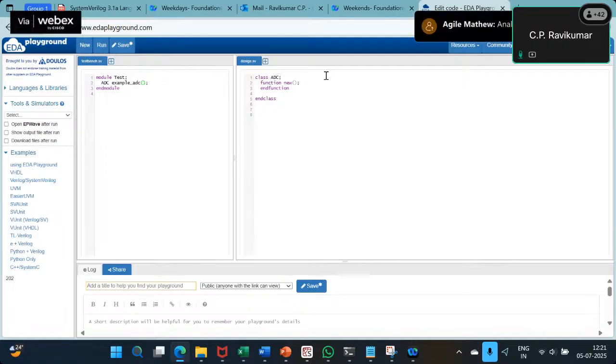Of course, we can keep a register. Okay. So maybe we can keep the accuracy or resolution is also something that we may have to give. Maybe we can say I want an 8-bit ADC, so that the ADC should be able to use that information to create an 8-bit register. Similarly, I should be able to say the maximum value is 5 volts and the minimum value is minus 5 volts. That is the range.